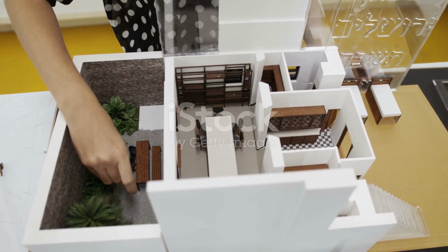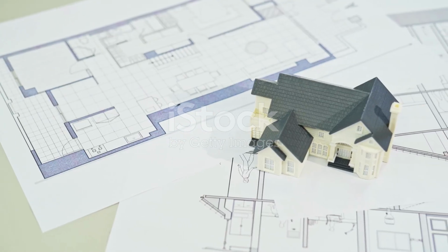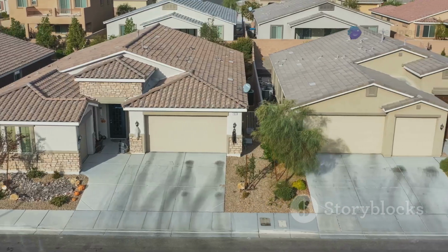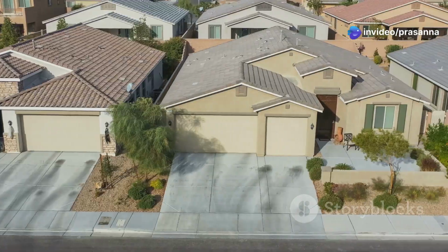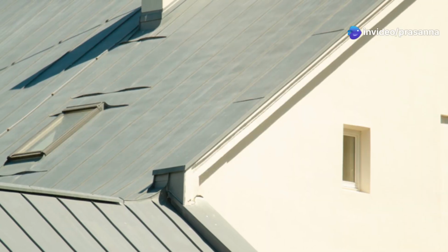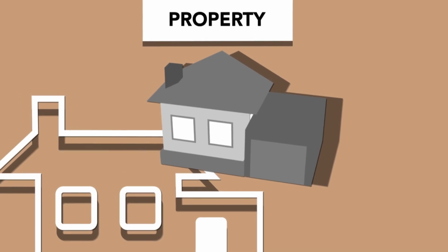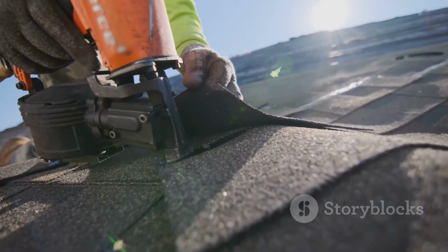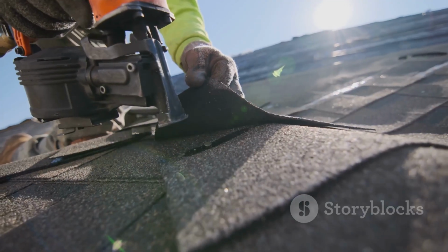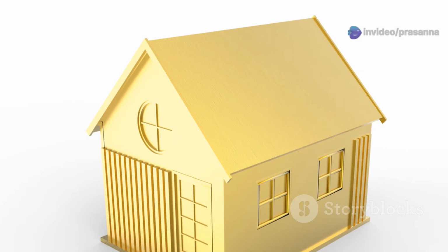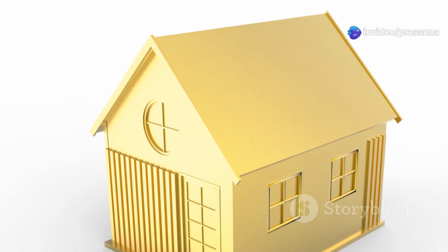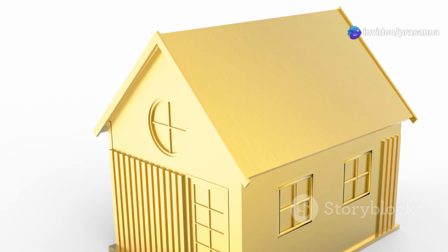Once your walls and floors are in place, the next major step is adding a roof. The roof defines the overall shape and style of your house. SketchUp offers several ways to create roofs. For simple flat roofs, you can draw a rectangle on top of the walls. Then, use the Push-Pull tool to give it thickness. For sloped roofs, like gable or hip roofs, the process is a bit more involved but still straightforward.